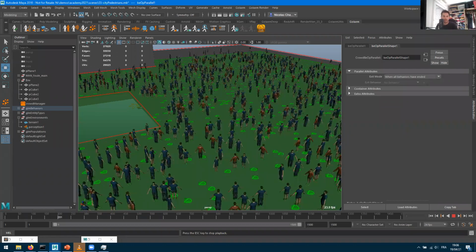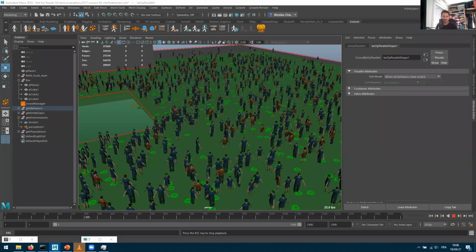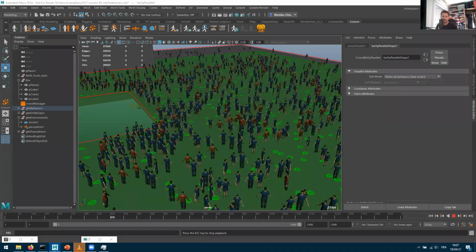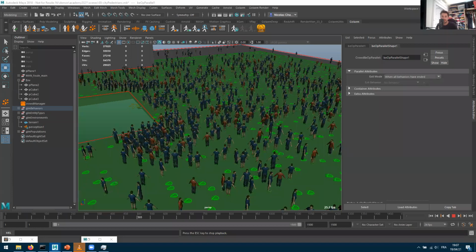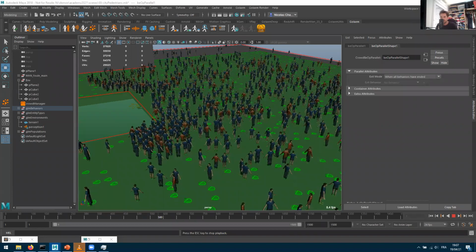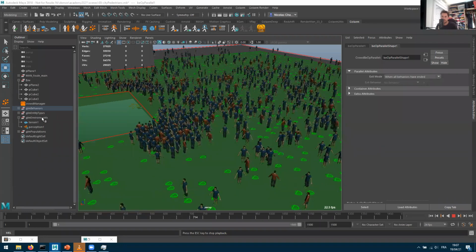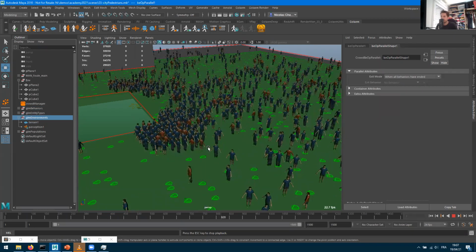Okay, so here we go. Let me review the questions quickly. I'm getting missing perception locator while using navigation behavior, the entities navigate blindly. It means that you deleted some of the nodes. So make sure that you created a terrain in your scene. Make sure that you do have a Golaem environment terrain here. And this is what's going to be used for the characters.